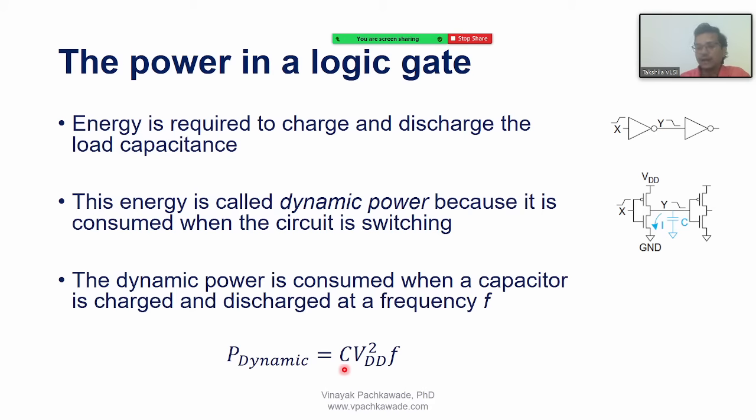Obviously, again, have a lower value of C, but sometimes it is fixed because you have to drive a certain amount of load. The value is fixed either by the external specifications or because the next circuit connected to the first circuit is already there. So you are driving the second inverter with this first inverter, and whatever the transistor lengths and widths are, that gives the physical size of these transistors, and that is fixed. You cannot change that. You have to have that load, right? So basically that capacitance can be calculated. So that is fixed.